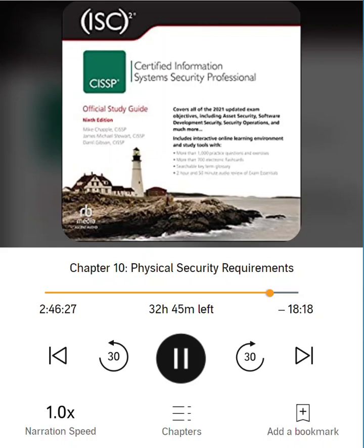The humidity in a computer room should ideally be from 20 to 80%. Humidity above 80% can result in condensation, which causes corrosion. Humidity below 20% can result in increased static electricity buildup. However, this does require managing temperature properly as well. The other number ranges are not the relative humidity ranges recommended for a data center.